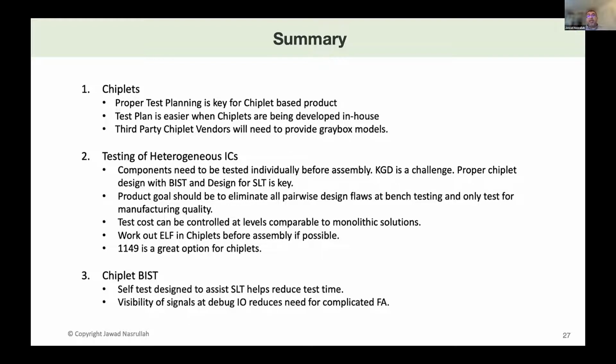That's one. The second one is if these interposers are going to receive subsequent components on top of them, right? By the way, this applies to base dies and 3D IC interposers and backend factories, all of it. So that's where, like Adam was saying, 1838, they have thought through some of these problems of how you stack other chiplets on top. So you probably have to think about that test scheme as well.